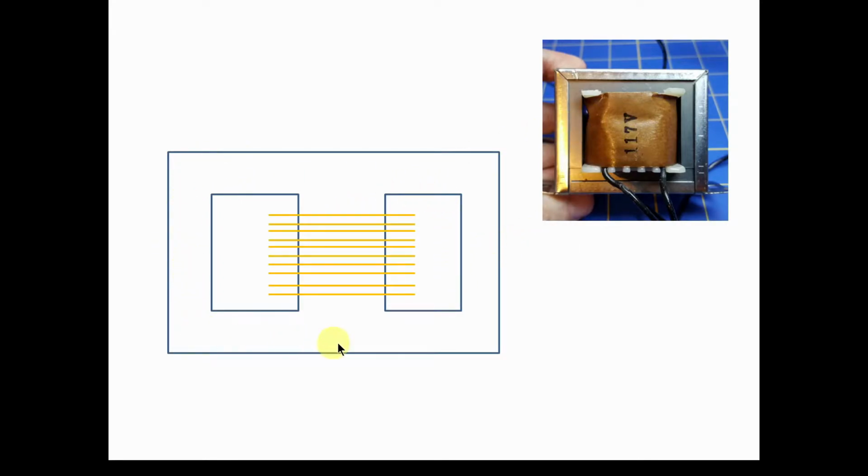And the iron core is shaped like this. They call it inverted E's or upside down E's. Like you can see an E here connected with an E on the bottom. And around the center of this, we've got the 2 windings. We've got the 120 volt on the inside, and wrapped around that is the 12 volt winding. So you can see we've got this path of the flux generated in the windings that goes through these inverted